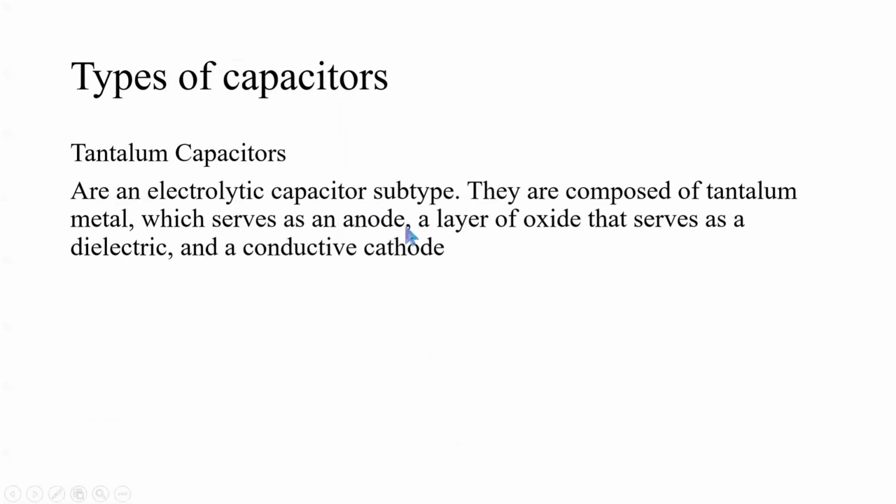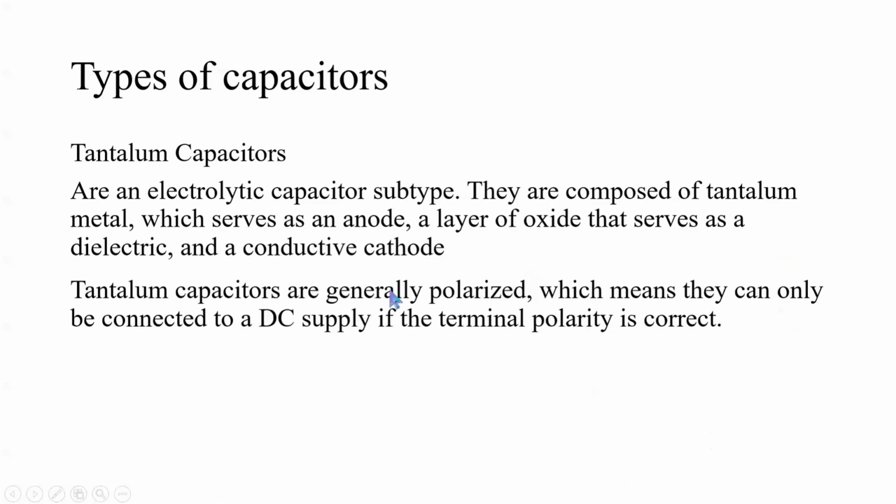Under electrolytic capacitors, we have what we call tantalum capacitors. This is an electrolytic capacitor subtype, and they are composed of tantalum metal, which serves as an anode, a layer of oxide that serves as a dielectric, and a conductive cathode.